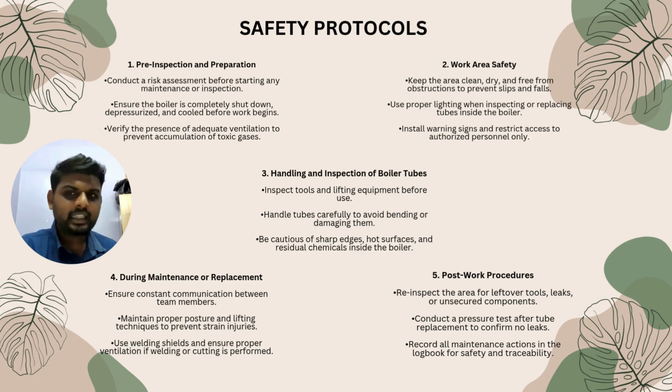Thirdly, the handling and the inspection of boiler tubes. Okay, let's see about the inspection. Inspect tubes for cracks, corrosion or leaks before installation. Then we need to use the proper lifting tools or cranes to handle the heavy boiler tubes. Then we need to avoid direct contact with sharp edges or hot surfaces.